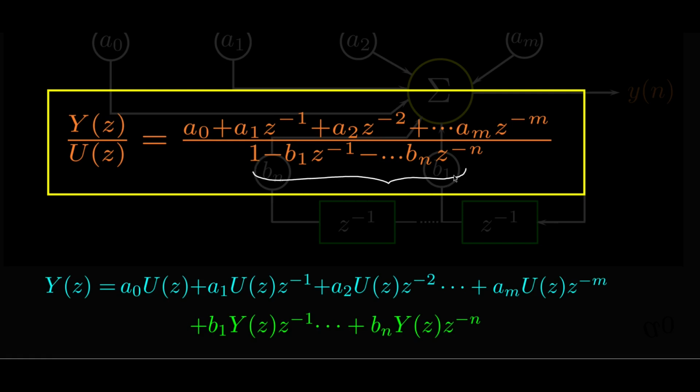So if I take the denominator and convert it into the pole zero form, you will see the roots z minus p1, z minus p2, where p represents pole, z minus pole 1, z minus pole 2, and so on, z minus pole n. Because there is a z to the power of n coming in, you will see that there are n roots, and this implies n poles.